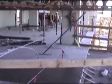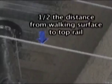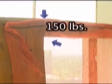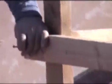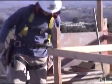If cable is used as a top rail, it must be flagged at not more than 6 feet intervals with a high visibility material. The mid-rail must be 1/2 the distance from the walking surface to the top of the top rail and be at least 1/4 inch thick. Intermediate members, mid-rails, and screens must be able to withstand 150 pounds of pressure in any outward or downward direction. Surfaces of guardrails must be smooth. Rails should not extend past a terminal post.